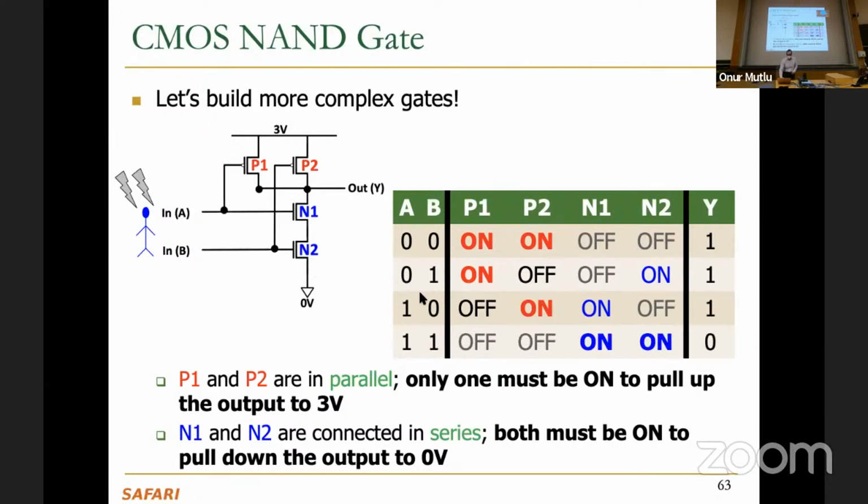And if you look at this, this is the inverted AND. The Y output becomes 0 only if A and B are 1. In an AND gate, output becomes 1 only if A and B are 1. This is the NOT of an AND, basically, right? Inverted AND. So of course, we analyzed every single case over here. That's one way of doing it.